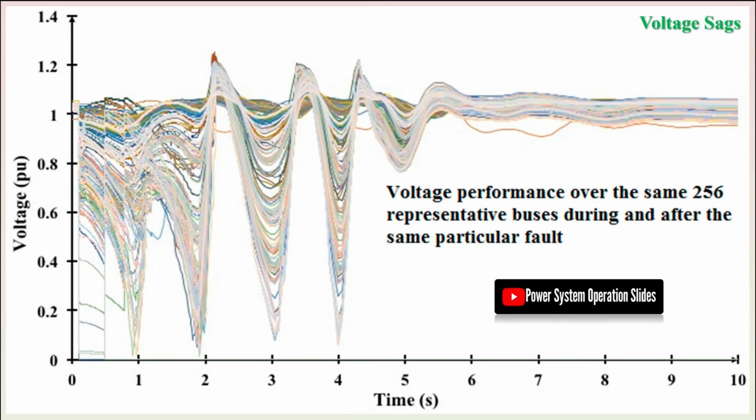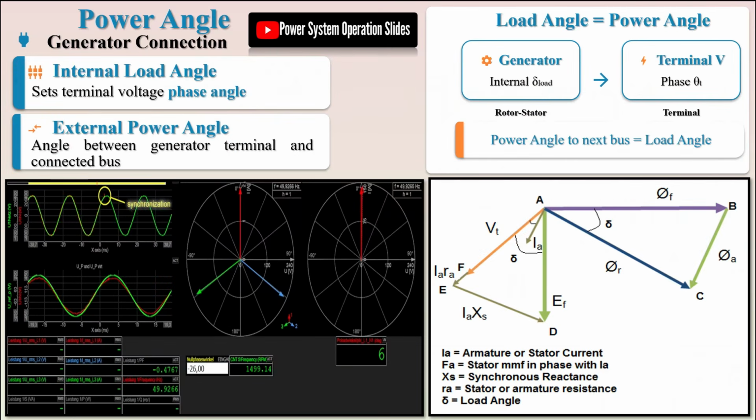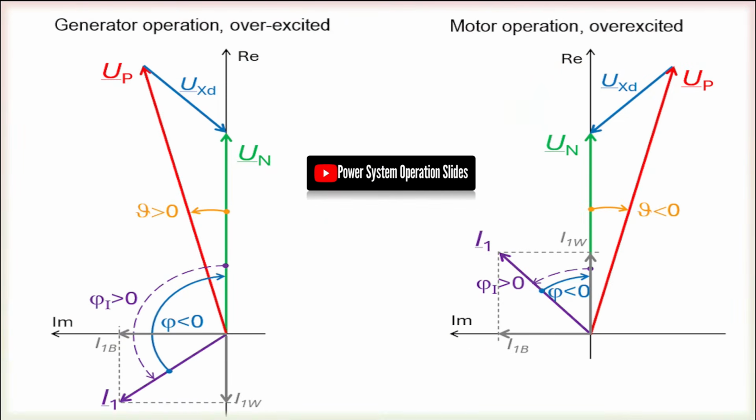The monitoring of power angles has evolved significantly with technological advancement. Historically, power system operators relied on state estimators using SCADA, supervisory control and data acquisition measurements. However, this approach had fundamental limitations. The measurements were asynchronous, with different time stamps from various locations, and the update rates were slow, typically one update every 1 to 5 minutes. This made it nearly impossible to obtain a true simultaneous snapshot of angular conditions across a large transmission network during dynamic events, severely limiting the ability to observe fast phenomena such as power oscillations or angular swings.